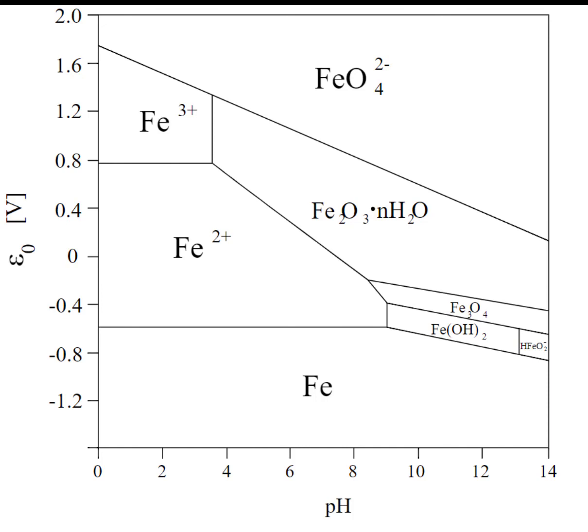Some of these oxides will be better than others at protecting the surface, and so we would be interested in whether some of these will protect our metal better. What you can see here reminds us of the situation we had before of different oxides on the surface. So if we look at this cut, let's call it pH 10, we can see we've got iron 0, then we've got Fe(OH)2, which would be stable if it can get onto the surface, but it's unlikely to be there.